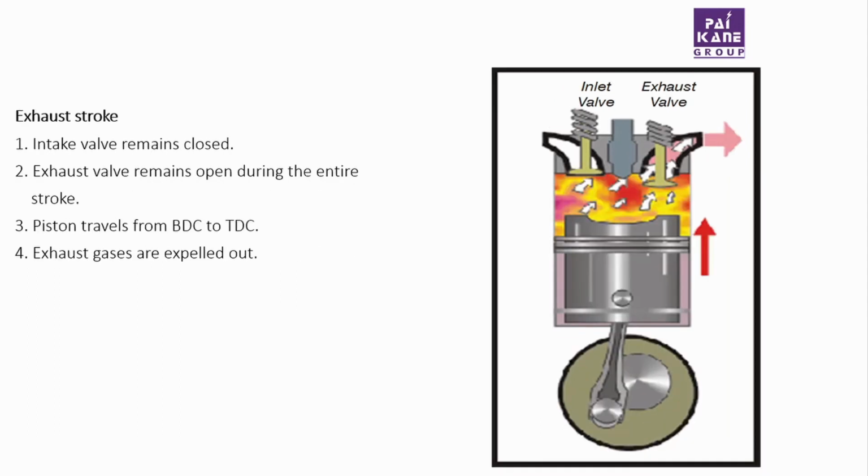And then we have the 4th stroke, which is the exhaust stroke. During the exhaust stroke, the intake valve remains closed. The exhaust valve remains open during the entire stroke. The piston travels from the bottom dead center to the top dead center and exhaust gases are expelled out.